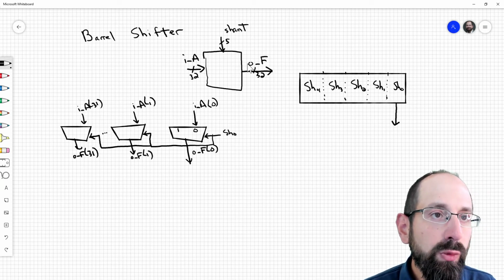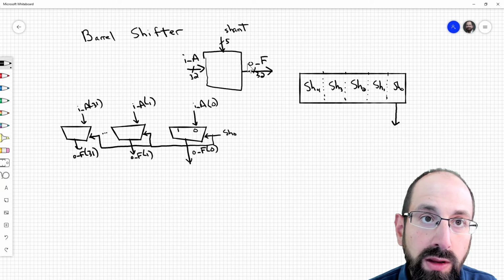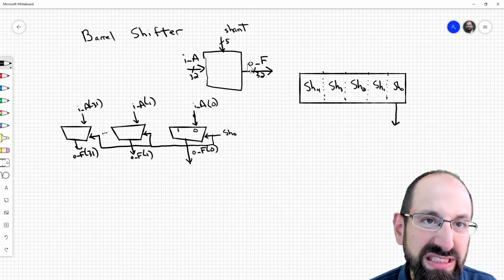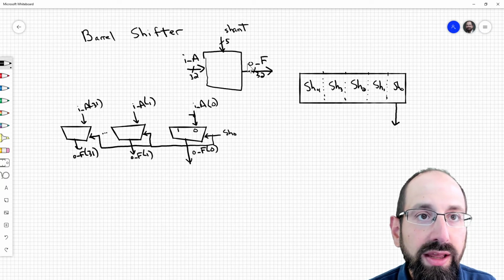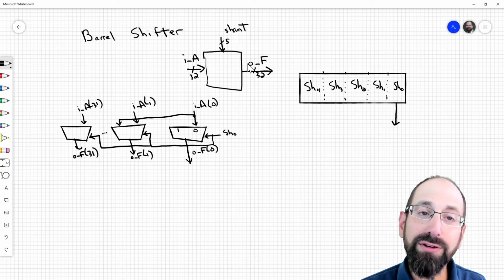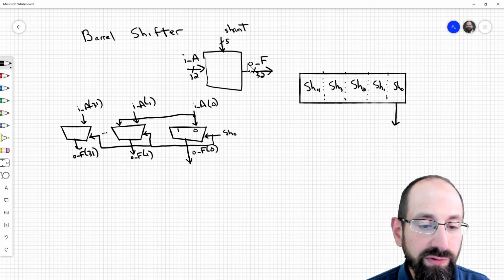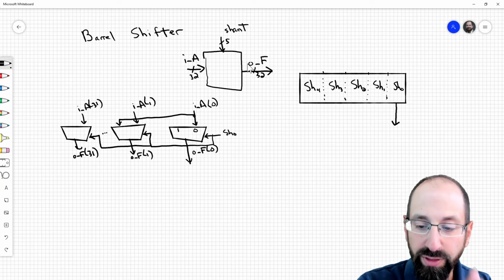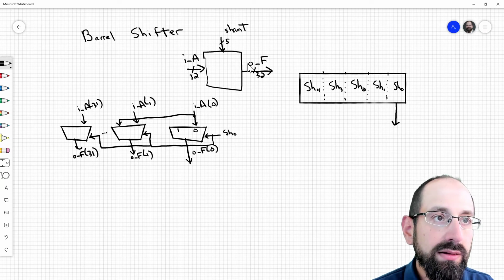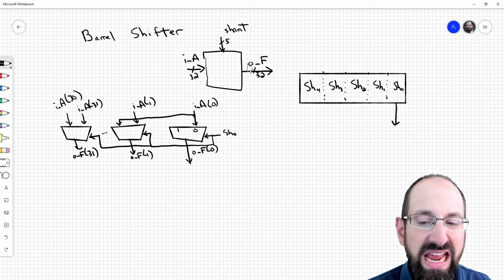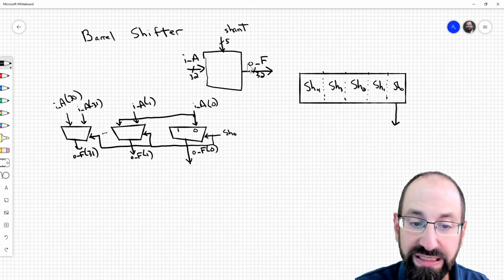Whereas if we actually do want to do the shifting by 1, and we're assuming we're shifting to the left here, the operation is exactly the same if we're shifting to the right. We just have to sort of flip the inputs and outputs around. If we're shifting to the left by 1, then that value should be connected there. Instead of O_F of 1 being I_A of 1, it would just be I_A of 0 because we've moved those bits over by 1. Likewise, although we can't draw the long arrow over, the other input to this would be I underscore A of 30. And everything would just be over by 1 if we're doing this single bit of shifter.